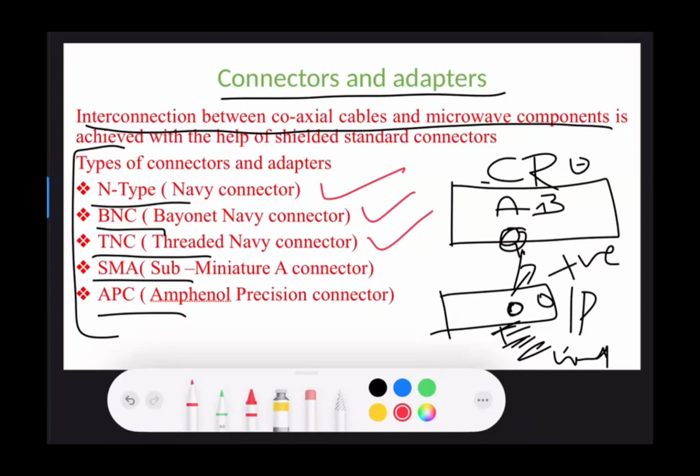There will be a loss of signal. That's why when you are conducting experiments in communication lab, relevant to microwave devices, if you leave some air gap in between the connectivity, then there will be huge loss of signal which you'll find in the output. So when you connect the cables in a microwave test bench experiment or in microstrip technology experiments, you should tighten the screws completely. If not, there will be a leakage of signal.